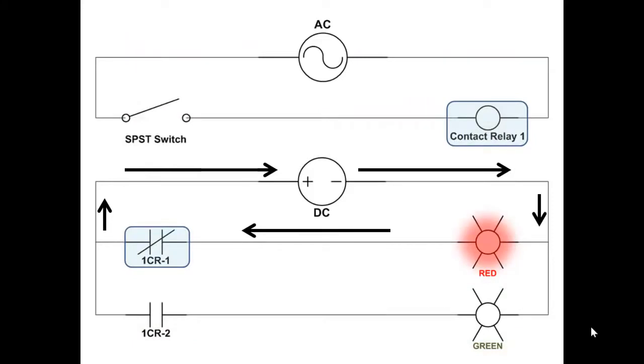So you have seen now a simple illustrated type diagram for an electrical circuit, and this is a more conventional style. Typically you divide up the AC from the DC, so all the AC is located on one sheet of the drawing set and the DC is located on other sheets, because the relay contacts very well will end up on a completely different sheet of the drawing set than the coil that controls them. You have to have very good nomenclature to identify what coil these contacts belong to.